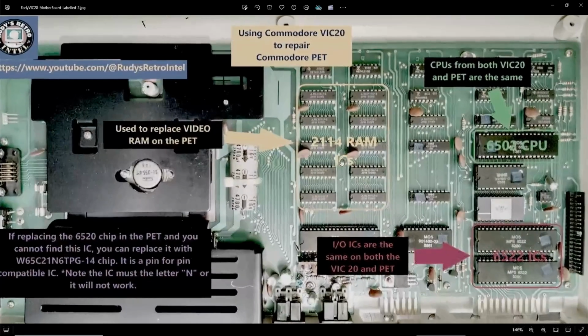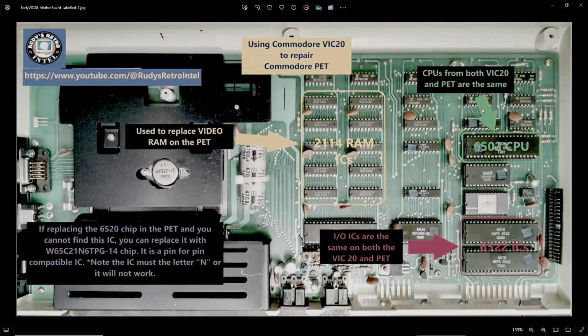So what we can do is from the VIC-20, we can actually pull out the 2114 RAM chips from here and use it for the video RAM. In PETs that have problems, one of the first things to look at outside of power is the fact that the video RAM usually goes, and you could use these ones to replace them.